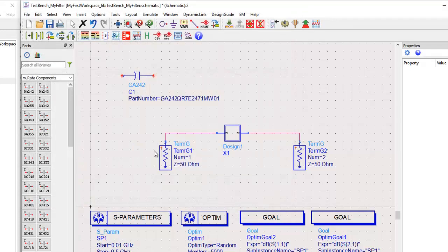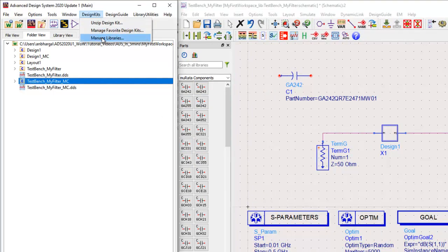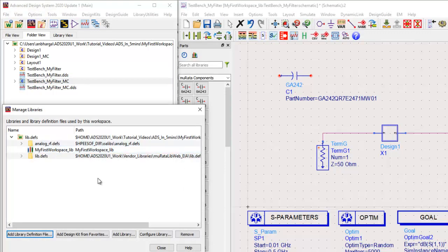Different vendors do this library modeling differently, so sometimes the structure will be different. These vendor models have a palette bit library. However, if we have already unarchived, we can simply go to Manage Library. Under Manage Library, every directory will have a library definition file.